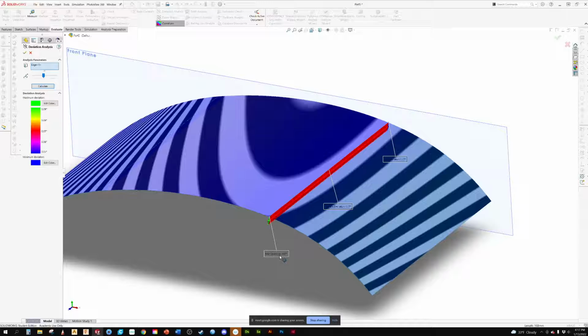0.07. Many times when I'm modeling, especially if I'm going to do a 3D print out of plastic, I'm going to say that's good enough. If I'm doing automotive, that's got to be 0, no matter what. So the curvature combs help you to see if things aren't perfect. So it's all the way of build, evaluate, and refine. And that's why you want to be methodical in making sure you add your tangencies and your curvature between the two and add all the relationships.